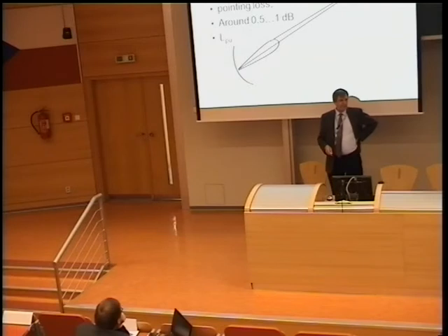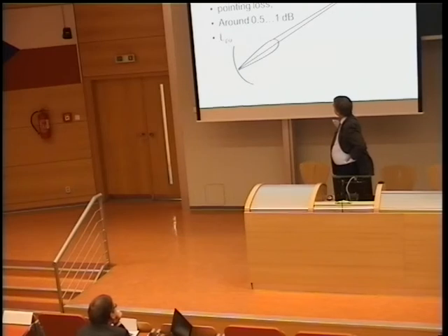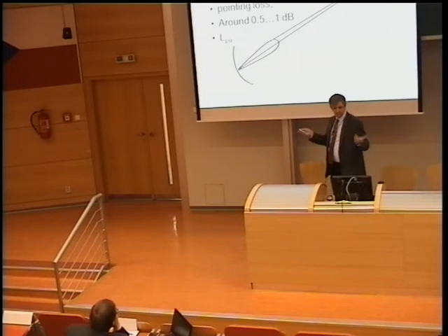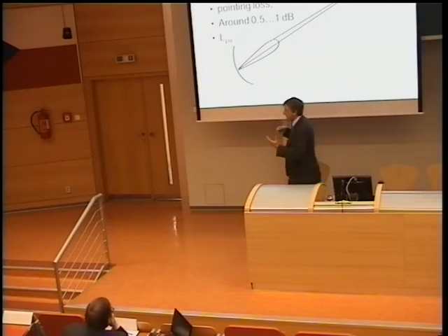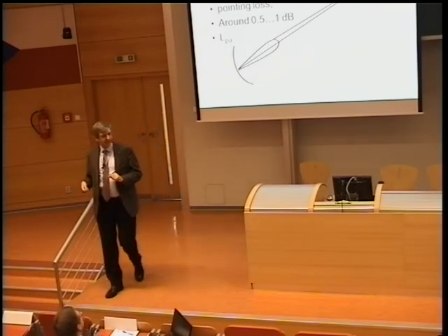Another loss is the pointing loss. So any antenna has a certain characteristic. So the lobe will have the maximum gain at bore side, and when we roll off here, it's getting less. And if now ground station antenna and satellite antenna are misaligned, then we get additional losses. So it depends on how well you are aligned. Usually this is not that high.